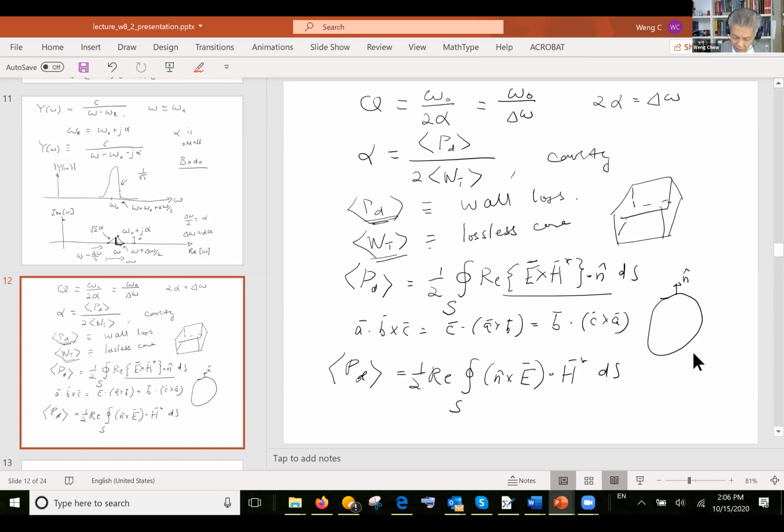Yeah, but I think I heard you say something wrong. If you have a PEC wall, is the electric field normal to the wall or parallel to the wall? If you have a PEC wall, how does the electric field behave around it? According to the boundary conditions, the electric field tangential components are equal, but they equal 0 because we have no electric field in the PEC.